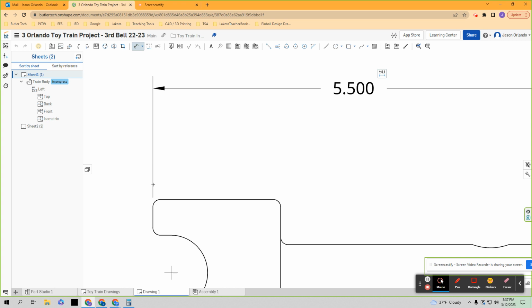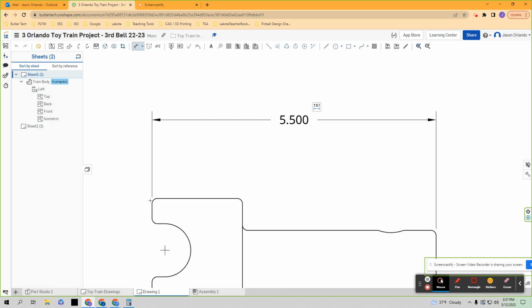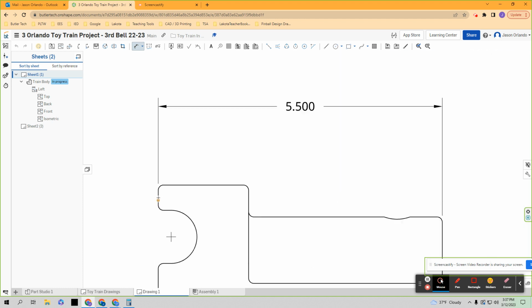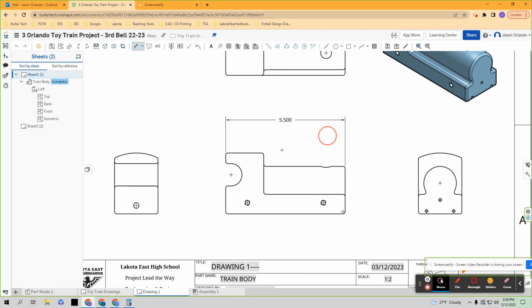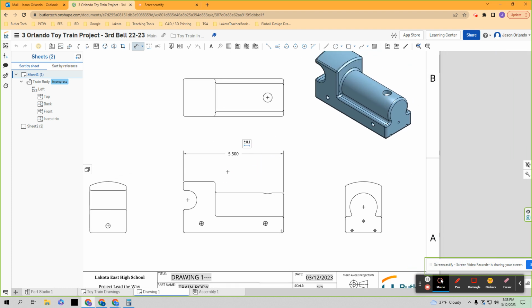So that extension line is going to run almost to where I select, but it's going to stop just short. It's going to keep that gap. I wanted this little white space here. And if I had chosen down here, this line would have run all the way down to here. Okay, so I'm trying to choose the highest segment or point on the side, the closest point or segment to the direction I'm going to pull that to manage those. So that gives me the overall width of the object, if I'm calling this width in here in the front view.